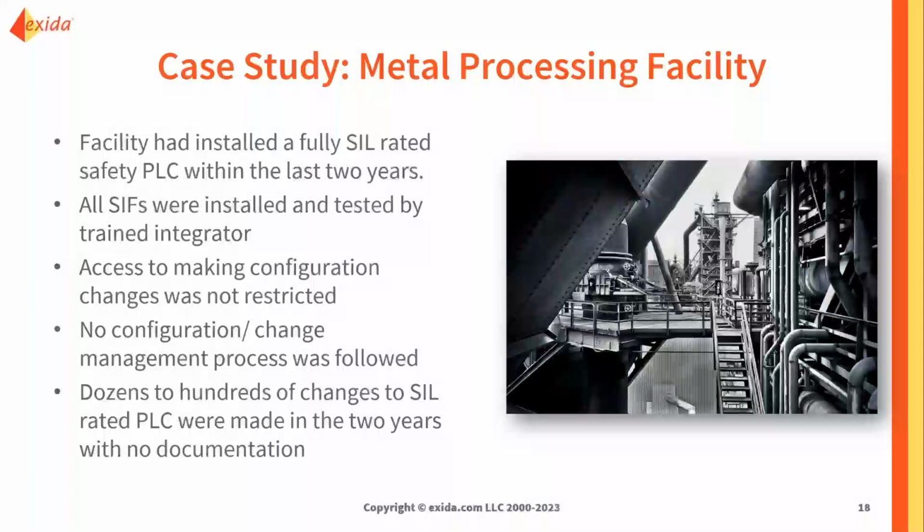And so really, you do all of this work up front, you get this fully SIL rated compliant system with all of the safety functions in there. And in less than 2 years, could even be as soon as a month or two, a whole bunch of unauthorized, untracked changes have been made. You have no idea whether or not the safety functions are still active, whether or not they're still effective the way they were designed. And so you've really now lost all of that safety benefit for the site until you do a full review of the logic, until you retest, revalidate everything, and implement change control.